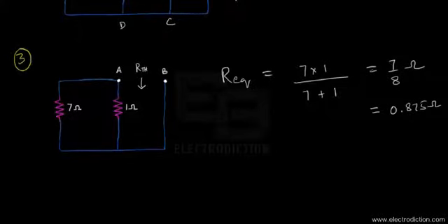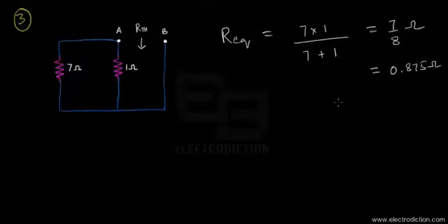So with this, we finally reach the stage where we can get our equivalent network using Thevenin's theorem. Finally we're here at step number 4, and here I'm going to draw the equivalent Thevenin's network. As Thevenin said, any network could be simplified to a basic voltage source in series with a resistor. That's the equivalent Thevenin's resistance. So we're going to include a resistor right over here. Okay, there we go. And now we're also going to include a voltage source. Where is the voltage source? I'm going to draw it right over here. There you go, that's a voltage source.